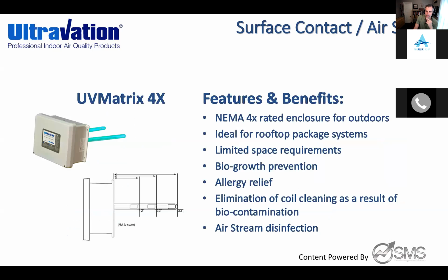If people are trying to get maximum disinfection rates for air supply, that's why that spreadsheet we sent you is so important. This is great for those smaller package units. I can get you 12-inch, 22, or 33-inch, in one or two bulb. This is how you start attacking those smaller areas where all I have to do is cut access holes and stick those bulbs in there. I'm not putting anything else inside the equipment, so we're really trying to minimize anything going into the airstream or into the equipment as much as possible.